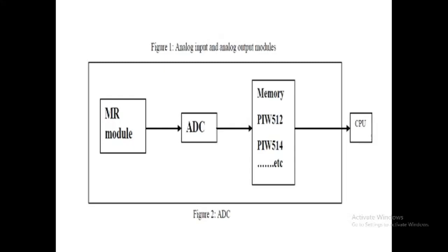If the function is executed without error, FC105 sets the RET_VAL, that is MW100. If this integer value is greater than or less than 0, then FC105 sets the output to HI_LIM or LO_LIM respectively. Then FC105 also returns an error by setting this value, and it stores the scaled value in MD200.